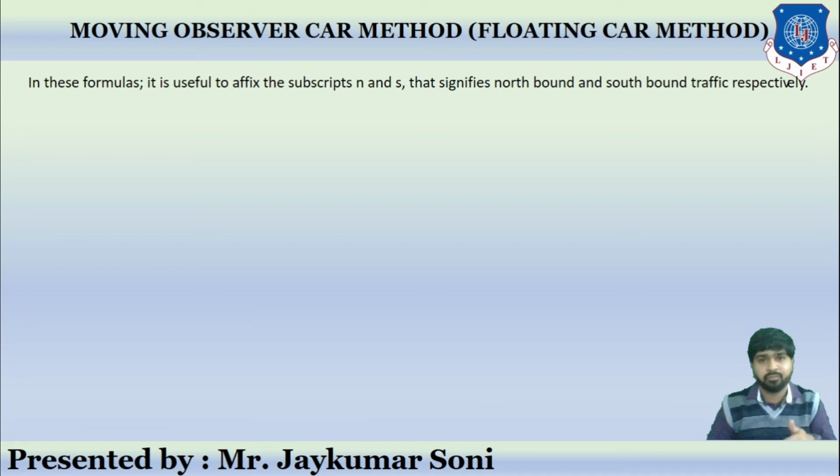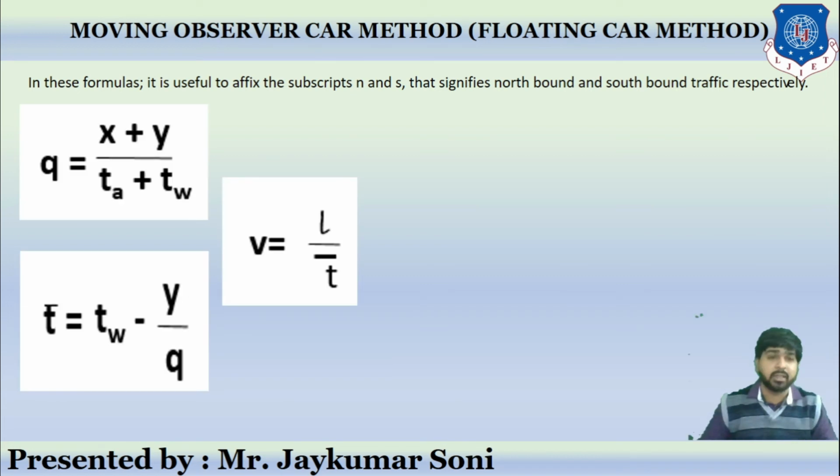Now, these are the basic equations that we have learned. q is equal to (x plus y) by (ta plus tw). t bar is equal to tw minus y by q, and v is equal to L by t bar. You have to remember these equations.